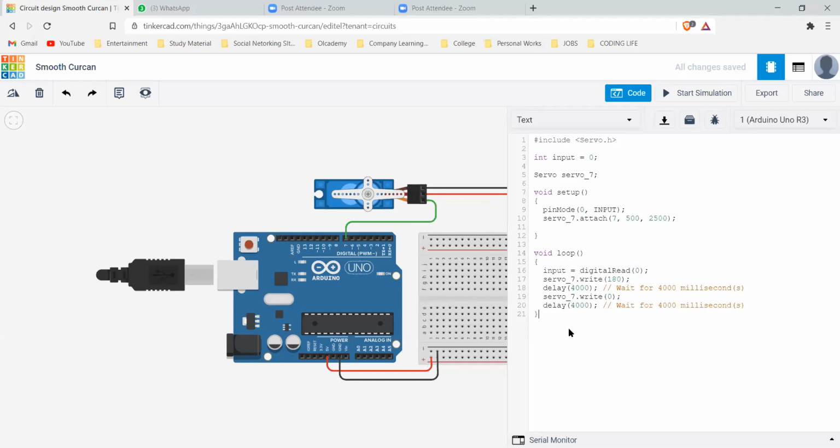So imagine you are reading a sensor input and you just write read sensor and then print sensor output. So you are printing the sensor output, and that's it, the project stops. You do not want that with an Arduino or IoT project. You want it to continuously read the inputs and outputs that are coming out of the system. So it constantly loops whatever code you have written, so that the system is constantly operating whenever it gets power.